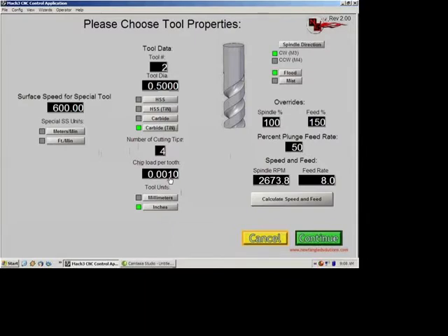You should change your depth per pass. The chip load per tooth will affect cutter life. You could bury a cutter, if it was strong enough, a foot deep in steel if you had enough horsepower and rigidity, but you never would want to take a really light pass if you had more horsepower to go deeper. So we'll leave this at about 2/1000ths.